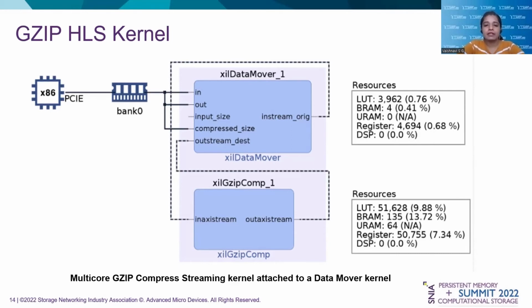There are 8 parallel engines of LZ77, Huffman encoder, etc. inside the GZIP compression kernel, which run simultaneously to improve performance. These kernels are designed in such a way that they can handle multiple compressed requests at once in pipeline fashion using a chaining interface. The kernels are also optimized at every layer internally, which makes them an ideal choice for this architecture. The overall resource utilization numbers for this design on the SmartSSD platform are shown to the right.